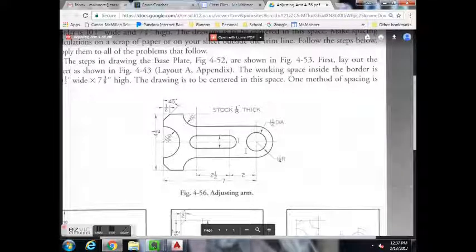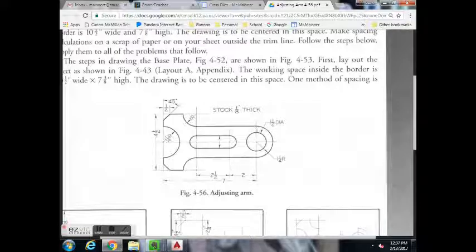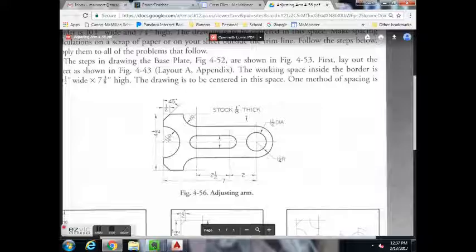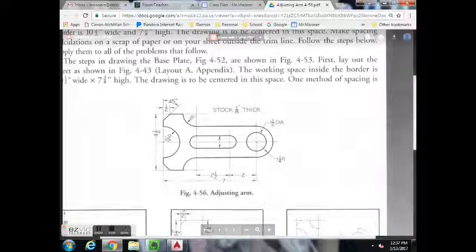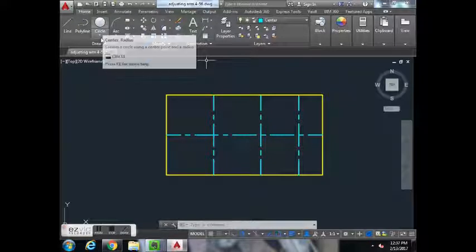You can see that the majority of this is made up of circles. So we have a circle, we have another circle, some more circles. So we'll start putting those in. We'll start on the right side. We have 2 circles that are given to us. One that is 1.5 inches diameter and one that is 1.25 inch diameter. So we'll do both of those, 1.25 diameter.